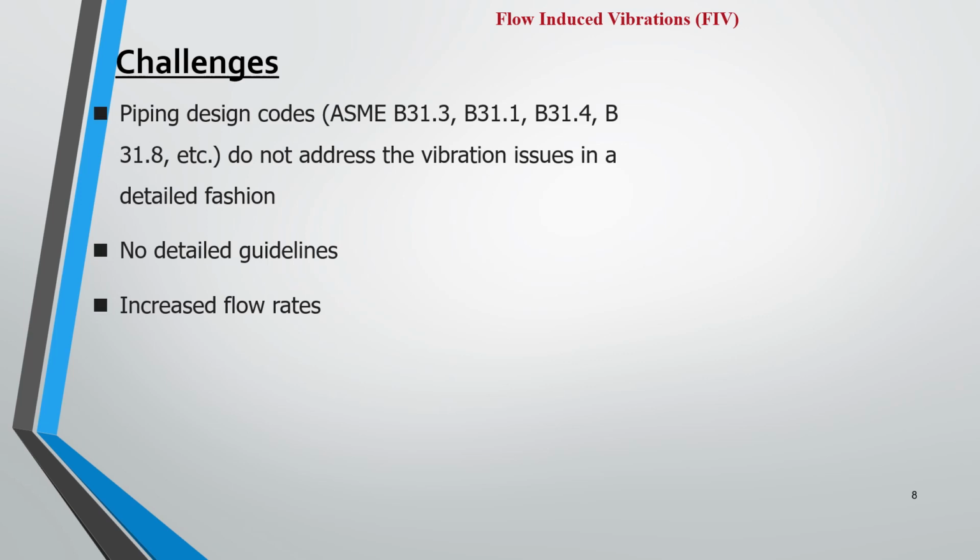the operation team increases the flow rates of the fluids to get maximum output from the piping or pipeline systems within a short span of time. So this increases the vibration tendency, and also one of the major causes in recent times, to optimize the cost, is the frequent use of thin walled piping systems.